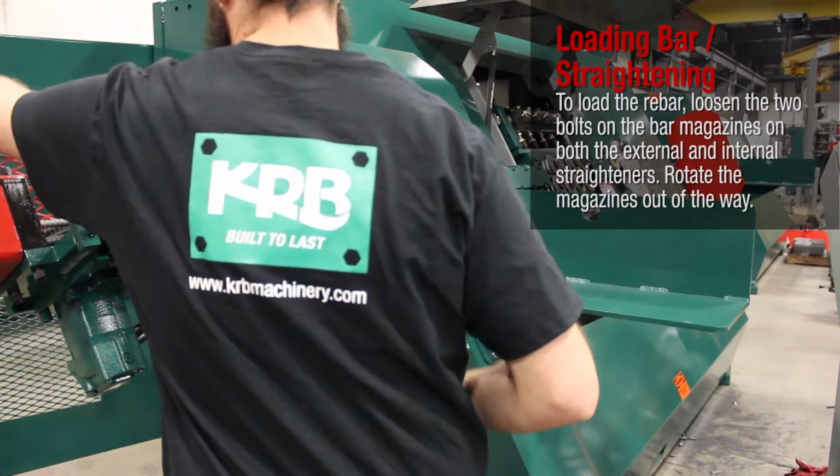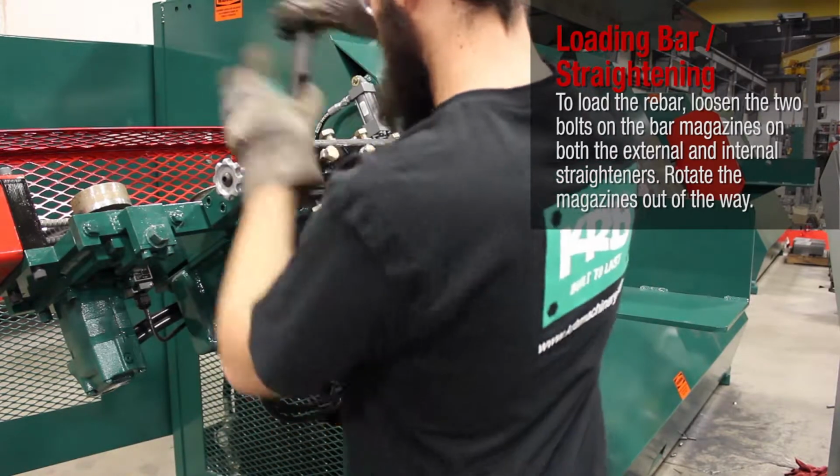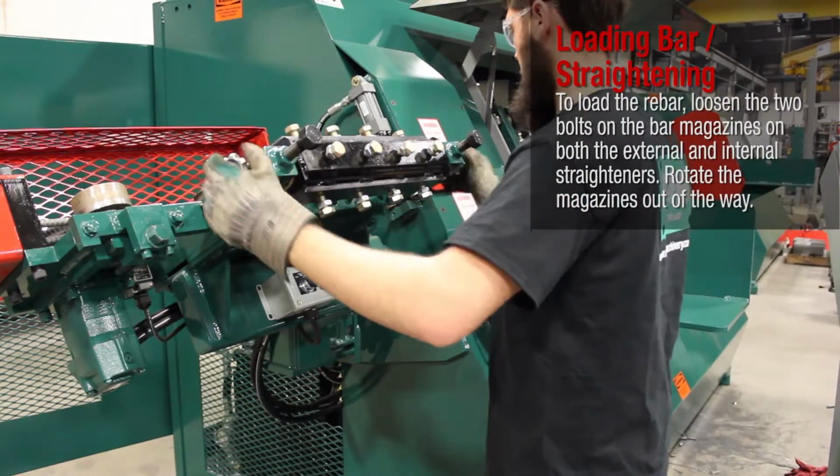Loading bar. To load the rebar, loosen the 2 bolts on the bar magazines on both the external and internal straighteners. Rotate the magazines out of the way.